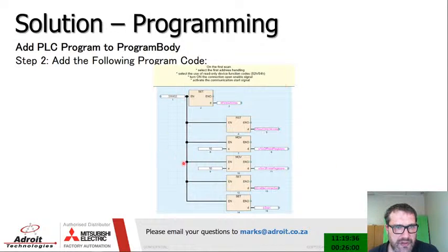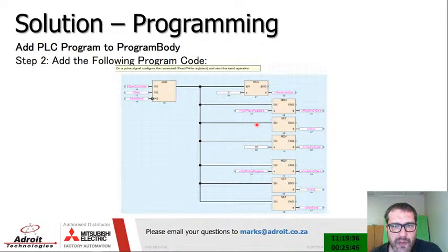Now, I want to show you guys specifically there. It says 10 number of registers and 10 number of registers. That first 10, those are the number of registers that you want to read, and that 10 is the number of registers that you actually want to write to. Okay. So once you set that up, then you are going to go to number 19 over there. Number 19, that's the write registers that you want to write to.